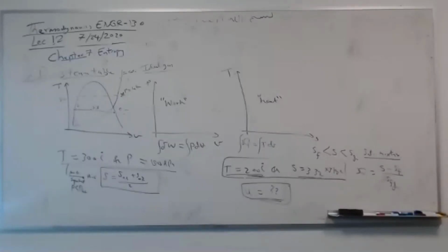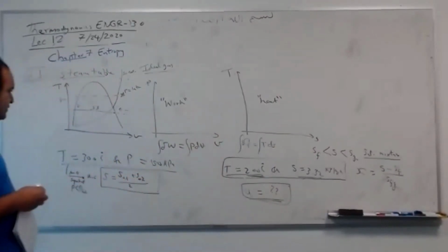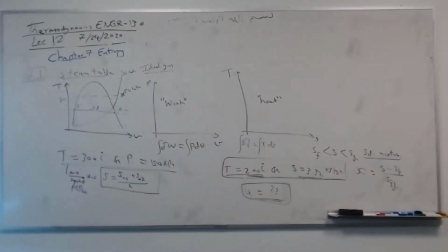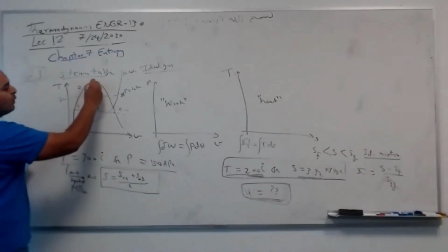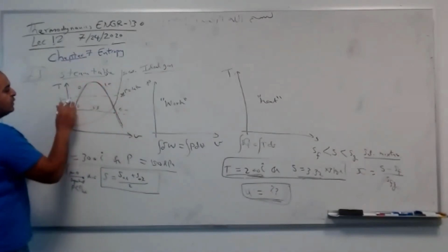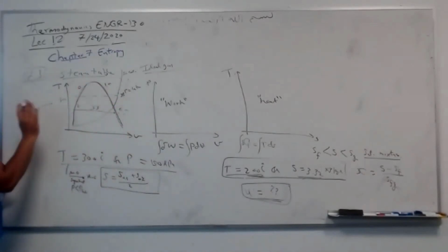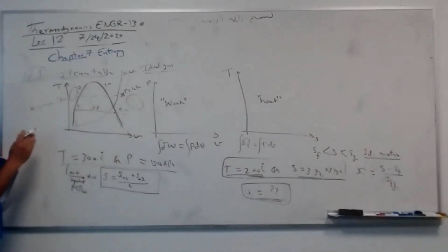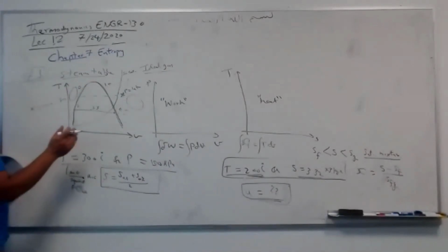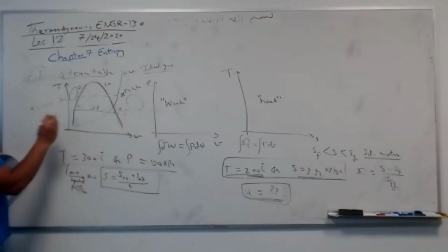You are good. So you go back here, so you can get X, 0.1, 0.2, 0.3. I don't know why almost all of you do not remember this. We have here X equals 0, saturated liquid, X equals 1, saturated vapor, no X here, no X there. So if you have a table, say there is no X. That's it. You got the total mark. In the subcooled region or here, there is no X. Some of you say X equals, for example, 12. I don't know how come. So X only in saturated mixture.